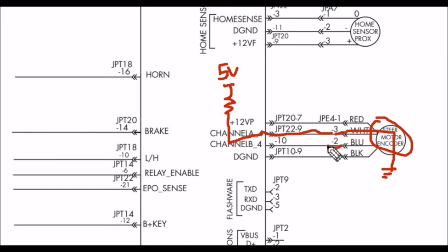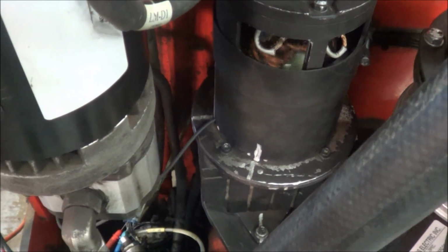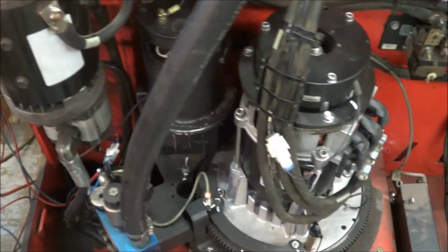And so this is a quick and dirty test again to check if my wiring going to my computer is okay, or is it still intact, because otherwise you would not see that 5 volt reference signal here at the connector end. Okay, finally replaced the encoder bearing on that steer motor right now, so there's no more codes.